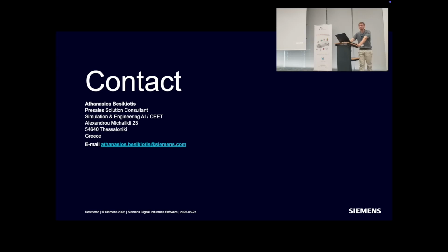Yeah. In this case, I'd say the HIDS AI simulation predictor is the tool to go for, because you will have a long-running optimization. And if you want to visualize the contours, it's a better case for the HIDS AI simulation predictor. Whereas for ROM AI, you have to rely on, let's say, some KPI values, for example, the maximum stresses, and so on.